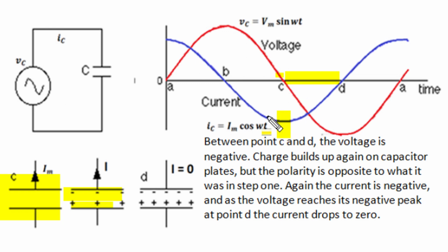When discharge current has higher magnitude, this reverse polarity charging is at a higher rate, and when this negative current becomes 0, the rate of increase of voltage in the opposite direction ceases and the capacitor will get fully charged in opposite polarity and the current becomes 0, and the same cycle of charging and discharging will take place onwards.